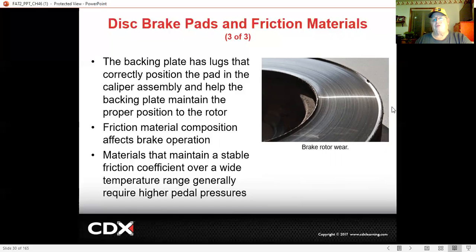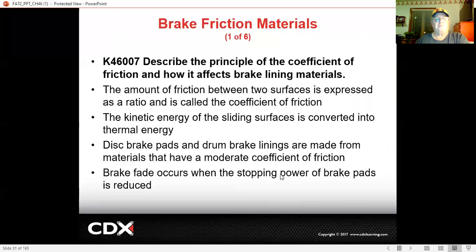But every time we had to replace the brake pads, our rotors looked like this. We had to replace the rotors also because they were extremely hard on the rotors. So anytime we replaced brake pads on those, we replaced the pads and rotors as a pair.